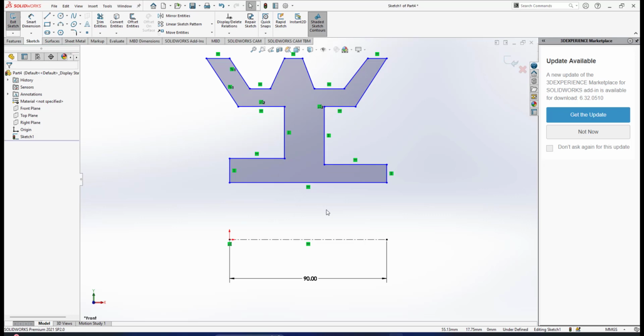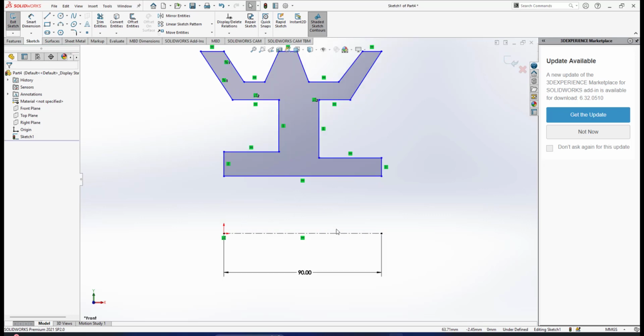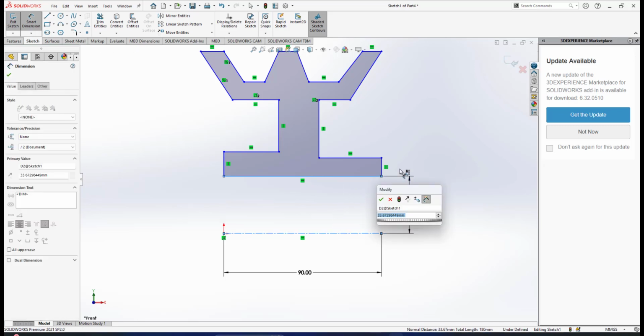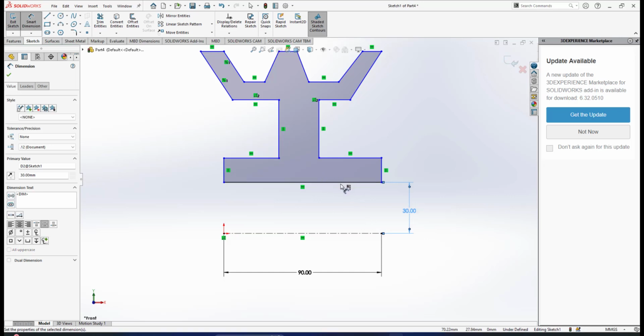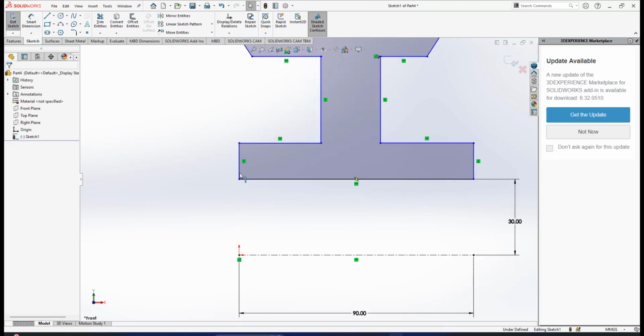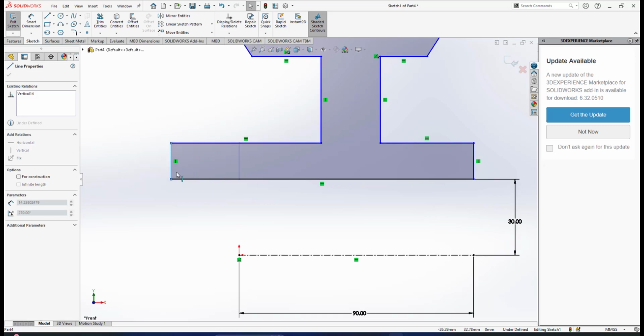One thing that I need to do first is that from here to here is 30. Since the diameter of the bore is 60, I put 30, so I know the position of my bottom edge here. Now I terminate my dimension. I need to make sure that if I drag this line, I haven't set the relation yet.